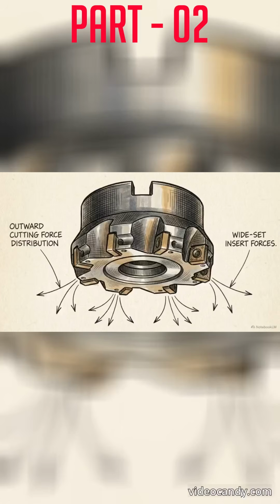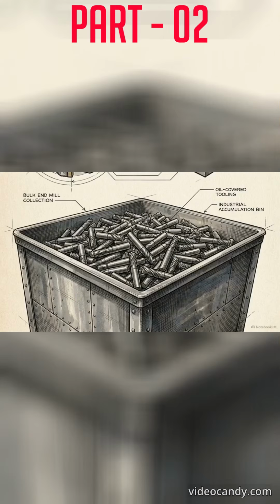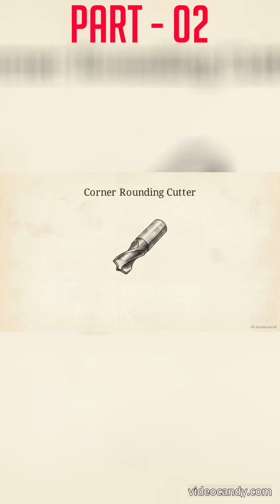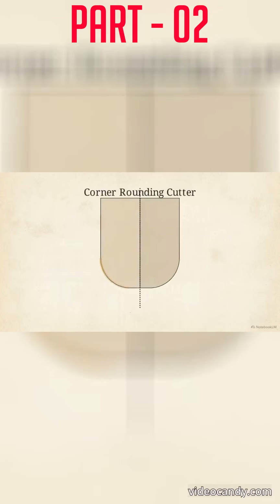cutting flutes to trace complex boundaries, while face mills distribute cutting forces across multiple wide-set inserts to clear flat planes efficiently. Standard cylindrical cutters are excellent for bulk removal, but they hit engineering limitations when a part requires specific complex undercuts or perfect external curves. That is where you apply a corner rounding milling cutter.